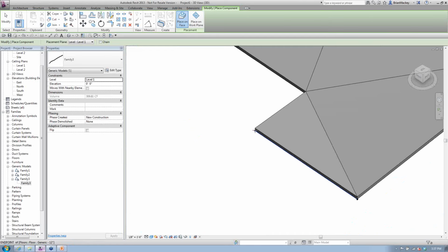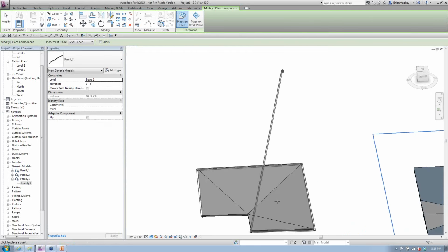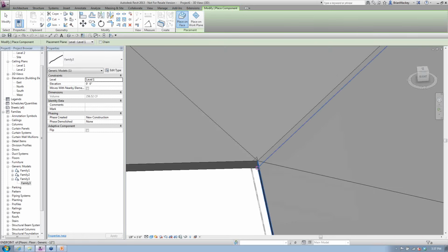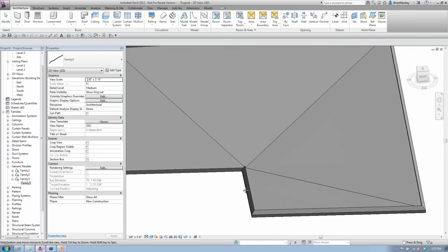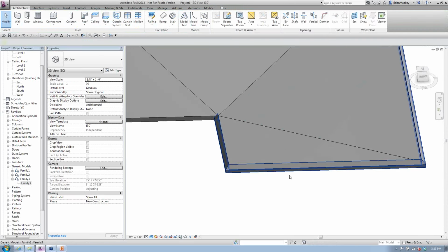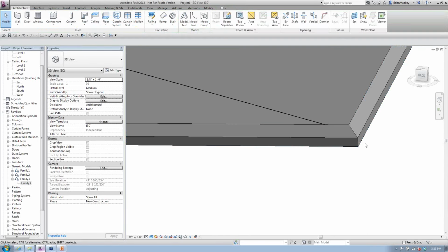So we'll cruise around to this, go to my inside point over here. I should have isolated this before I started this. So it's not a 6-point family, but you guys will get the gist. So now I can come through here and start doing that, and it's going to go up and down and around and miter nicely around the corners for what I'm doing inside of there.